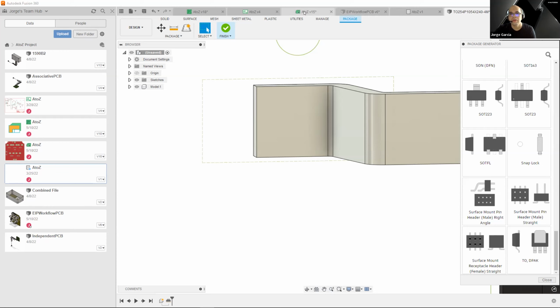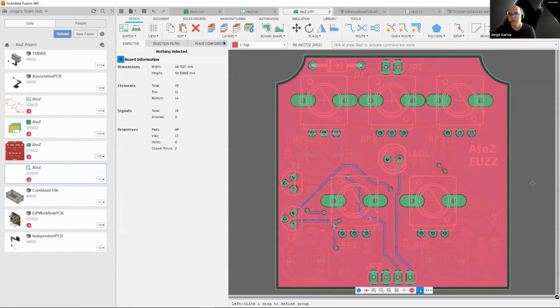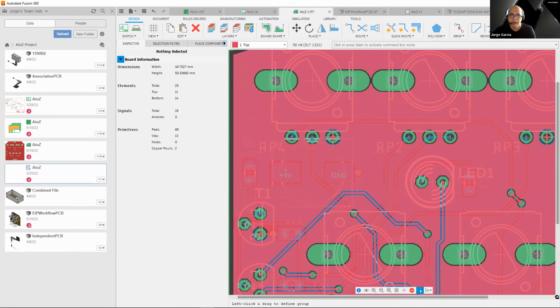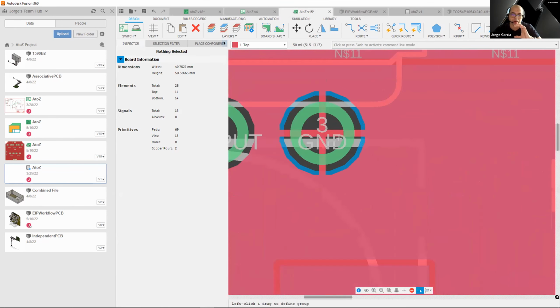So what you would do is, and you'll see it here, there's a few here that have, this one here. Basically the pad, the big pad, is going to have a net assigned to it. It'll be ground, whatever you call it. When you create the polygon pour, it gets a name. If the names match, it'll connect using spokes like this.